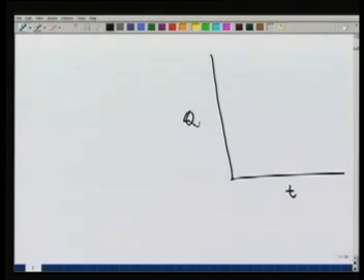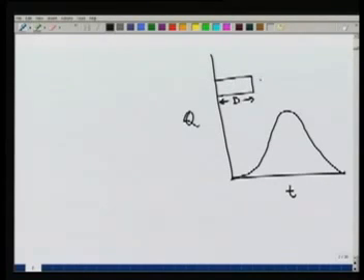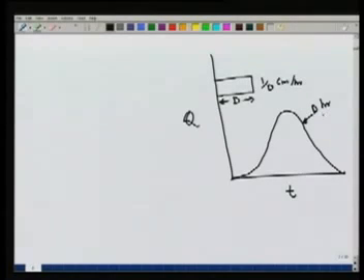By now we are familiar with the unit hydrograph shape. So let's say that we have a unit hydrograph for an ERH of certain duration d, and of course the intensity would be 1 by d centimeter per hour. Now if we reduce the duration of the rainfall, and increase the intensity in such a way that the total amount of rain falling is still 1 centimeter, we would get a different unit hydrograph. So this is a d hour UH.